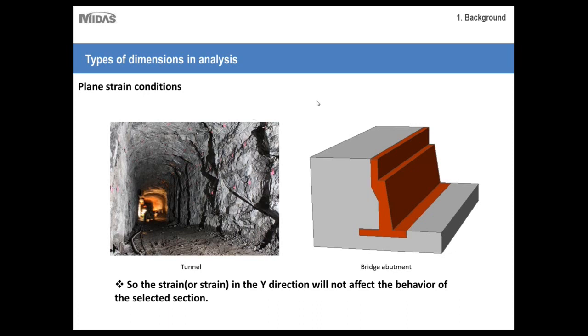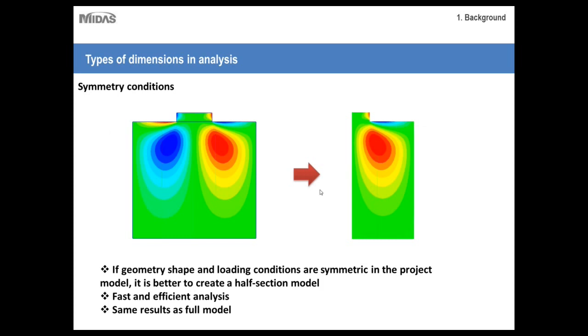So just keep in mind that whenever project geometry is symmetrical in the longitudinal direction, or close to symmetrical, 2D analysis is especially useful to help you save time and effort. And then let's go over some other symmetry conditions. As you can see, this is an embankment type project where it's symmetric just going along this axis here.